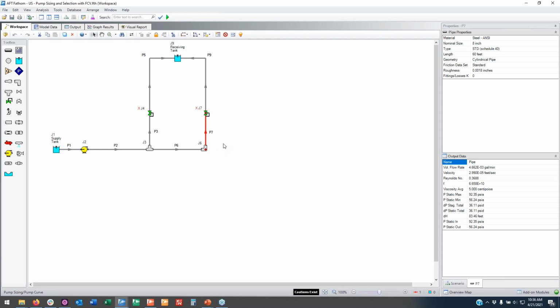And I think that's kind of cool to see how that Bingham plastic works out in your system with multiple flow paths. And it's a good reminder that in a real system, which has more complications than even this example, you have parallel, you have in series flow paths, and a very networked system, there's a potential that some of your legs might not actually see flow, just because the system can't meet that yield stress demand.